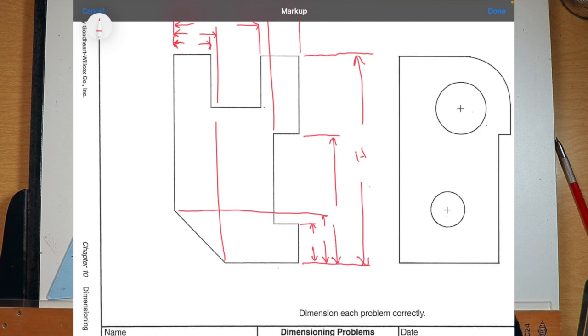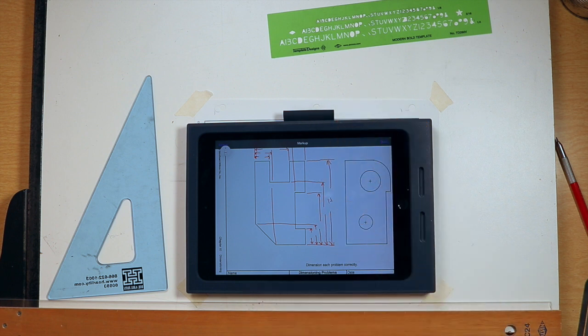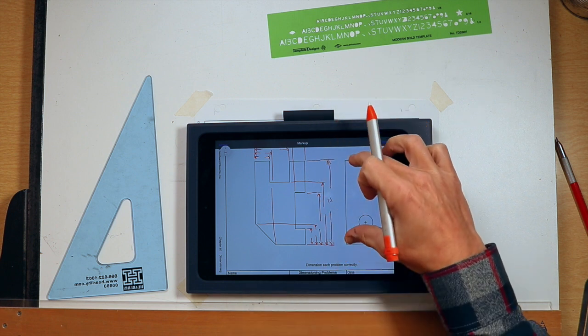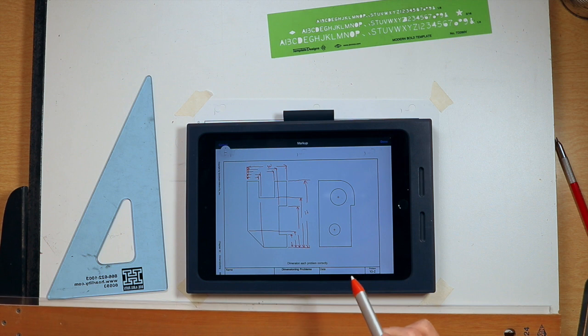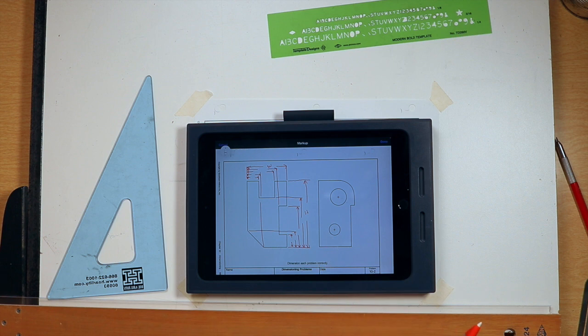I'm going to need the size or the depth of this notch. And then I have the overall height. So that one is basically done. So this brainstorm shows me I need 1, 2, 3, 4, 5 different height dimensions, and I'm going to need 5 width dimensions. Now I could change where I actually position these.